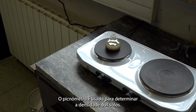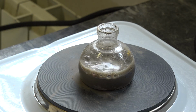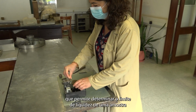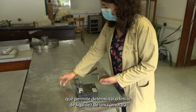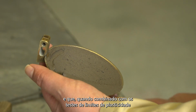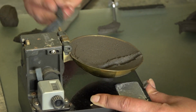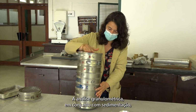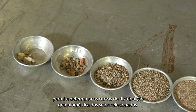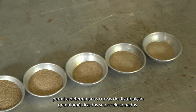A pycnometer is used to determine the specific gravity of the soil. The Casagrande test is a standard test to determine the liquid limit of the sample that, combined with the plasticity limit test, allows for the determination of the Atterberg limits. The sieving analysis, combined with sedimentation, allows for the grain size distribution curves of the selected soils.